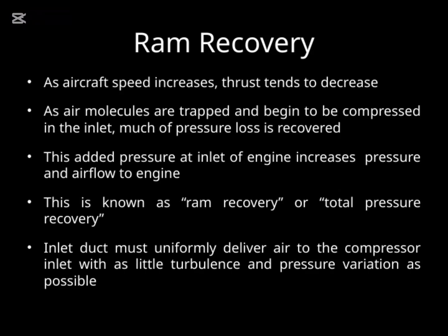This process is crucial because it means we're able to convert some of that kinetic energy back into pressure energy, effectively boosting the pressure at the engine inlet. This increase in pressure at the inlet is what we call ram recovery, or total pressure recovery. It's a key concept because it directly influences how much air is delivered to the engine's compressor. More pressure and airflow mean better engine performance.